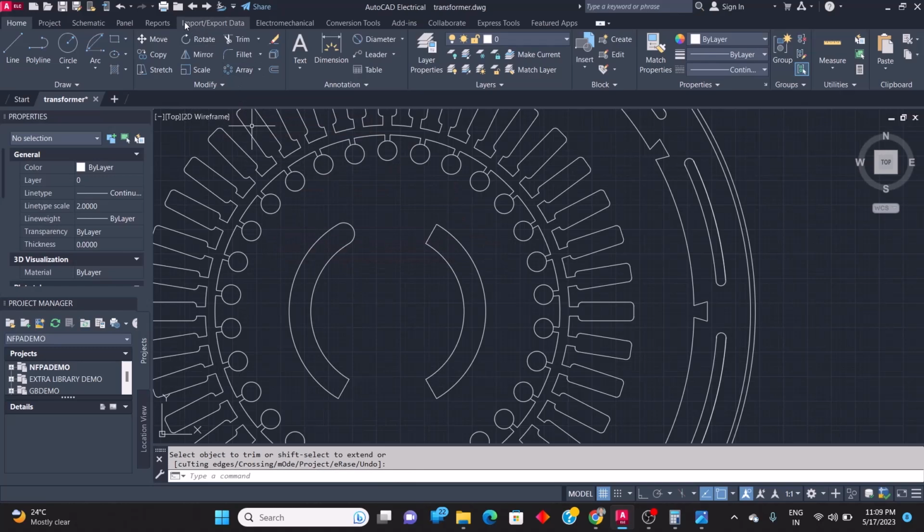So simply now I'll copy this point and pick up from the center. It is not working, so we have to take this and draw a circle. Again draw a circle, again draw a circle. Now trim command, TR, remove the unwanted parts. This is the air duct, rotor air duct. This is done.